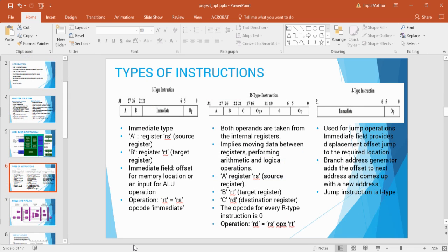There are three types of instructions that NIOS 2 can handle. The first one is called the I type or the immediate type, examples of which are arithmetic and logic instructions like addi and andi, branching instructions, and load and store instructions. R type instruction examples are ALU type, which are add and NOR, comparison instructions like CMP-EQ and CMP-LT. Custom instructions are also R type. The third type is called jump instructions, like call and JMPI. They transfer execution anywhere within a 256 MB range.